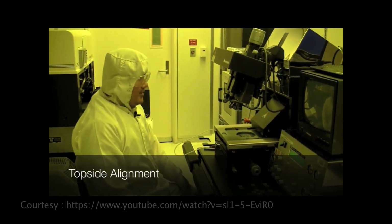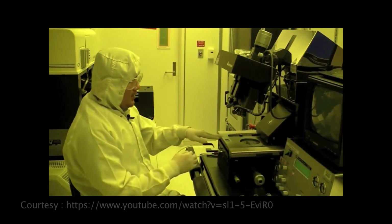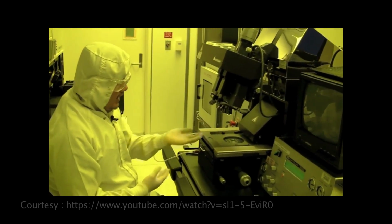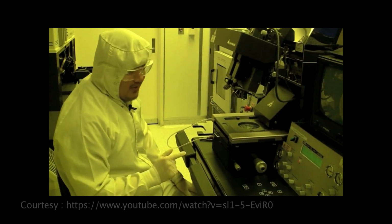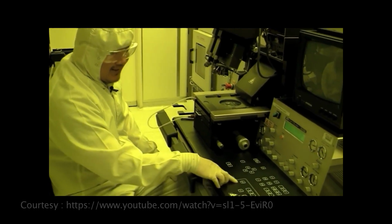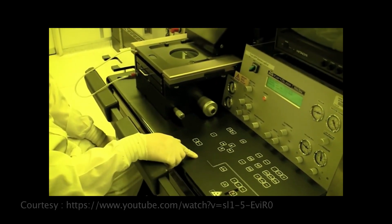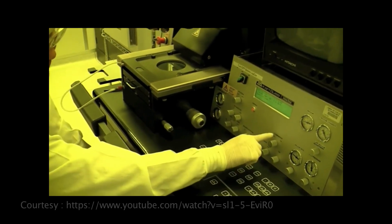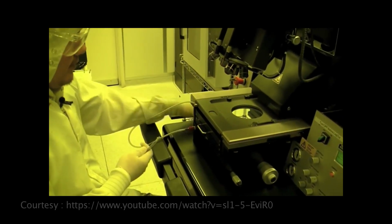What we're going to do now is topside alignment, by using the microscope on the top to align to the wafer that's underneath through the glass. So to do topside alignment, we need to move the backside microscope. So we press this button, that turns it off. Also, we need to put the illumination to the top side. And then we can load our wafer in.